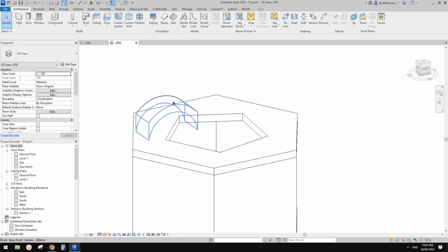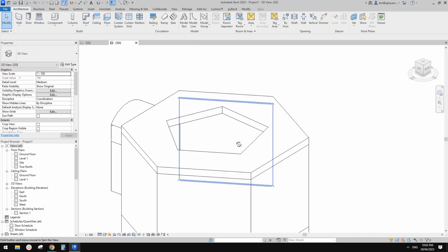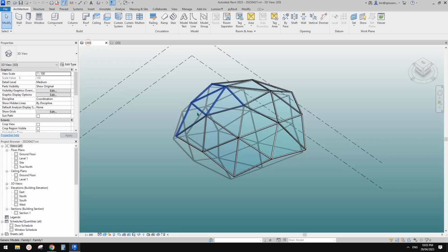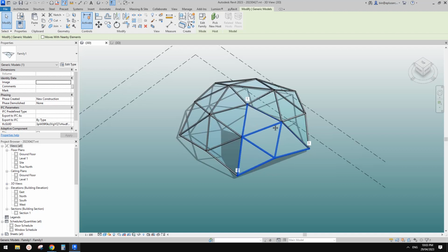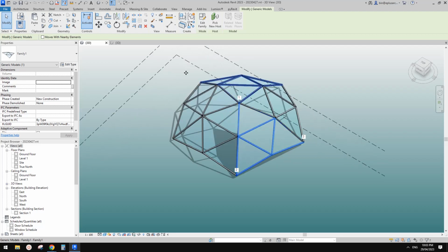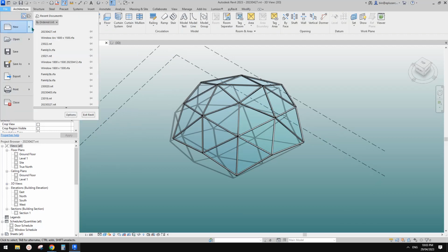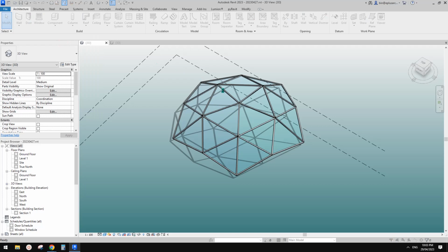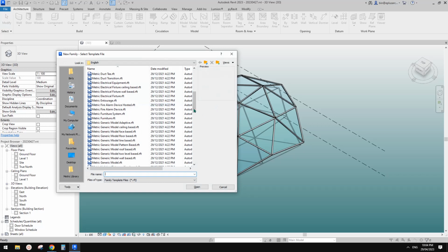So now we need to create this. Hang on. Okay, so looks like I used 1, 2, 3. Okay, so what I did is a 1, 2, 3 adaptive family. So let's do it. First we need to create a family. So let's use generic model adaptive.